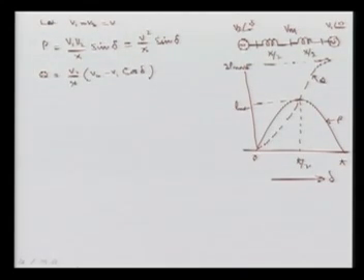I want to show you the midpoint of the transmission line, so I have put the reactances, half on both sides of this midpoint Vm, giving the total reactance of the line. I am ignoring the losses, that is the resistance of the line. This system's angle is 0, and the angular separation between the two is delta.